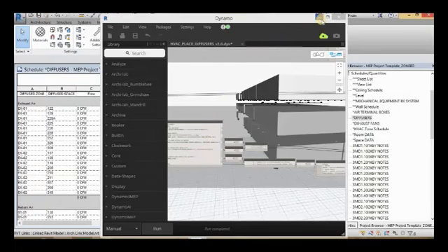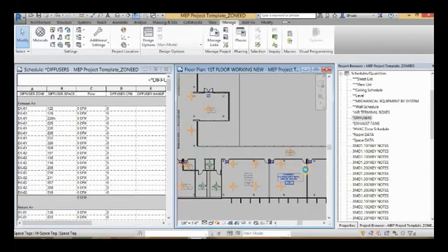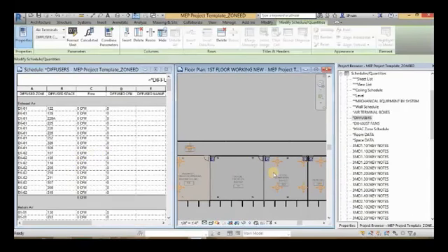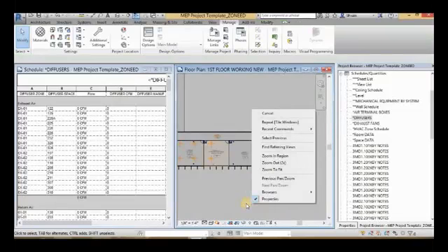Pull this back up. And as you can see, just like the top room said, all these are following those same type of rules. I don't know why they're not showing up here. I think it's a view range issue, so let me fix that real quick.